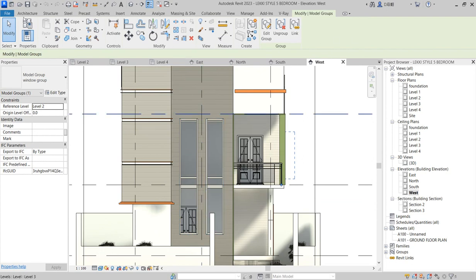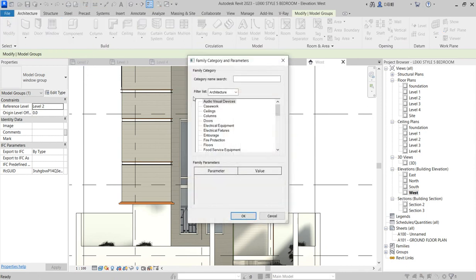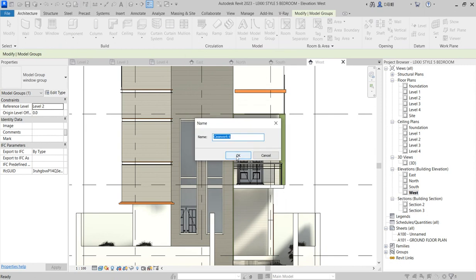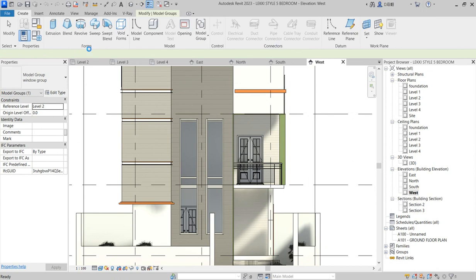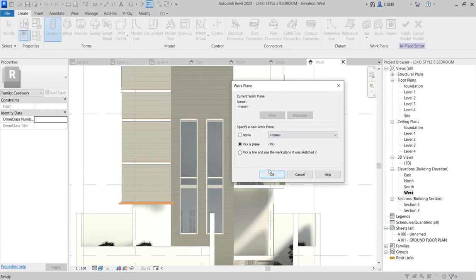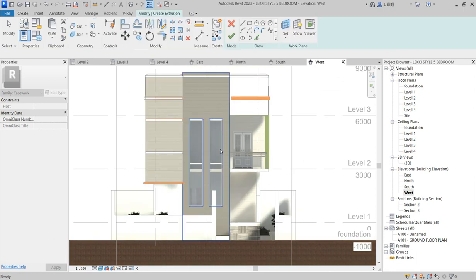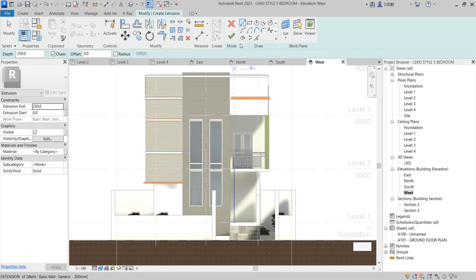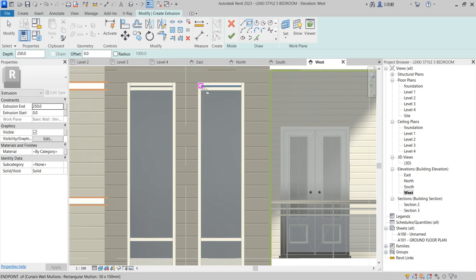Around this place, you click on Architecture, Model In-Place. From Model In-Place, you click on Work and Casework. I'm using this one, just leave it like that, case paint. You can rename it if you choose to do so. I'm using extrusion. I'm not picking anything, I just want to pick a plane of itself. So I drag around and choose the one that will select a rectangular position for me. Here I'm using rectangle to create that inner bond.